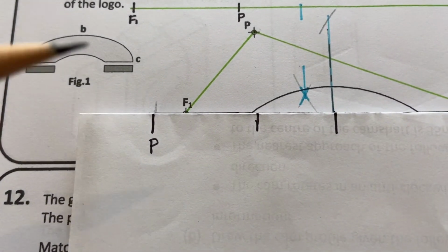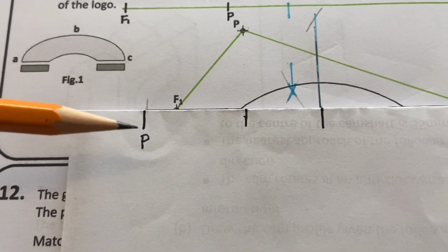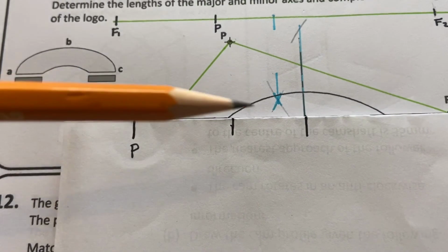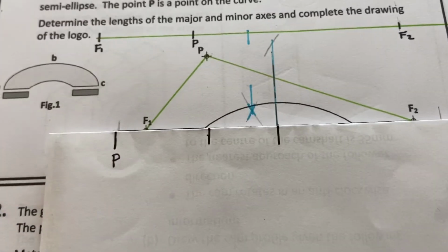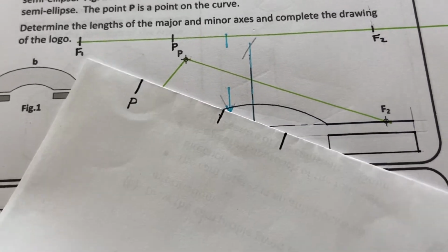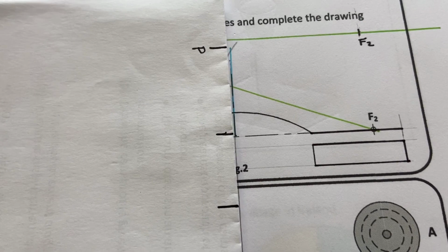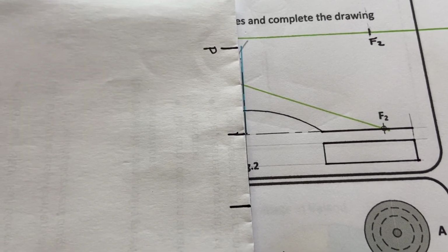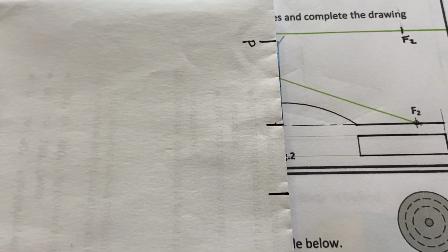So with a scrap piece of paper, and out here at the end of the major axis, mark a point P. Take half the major axis and mark that on your piece of paper. Then moving around the piece of paper, that P is on the end of the minor axis, then take half the minor axis and mark it on your piece of paper to make a trammel.